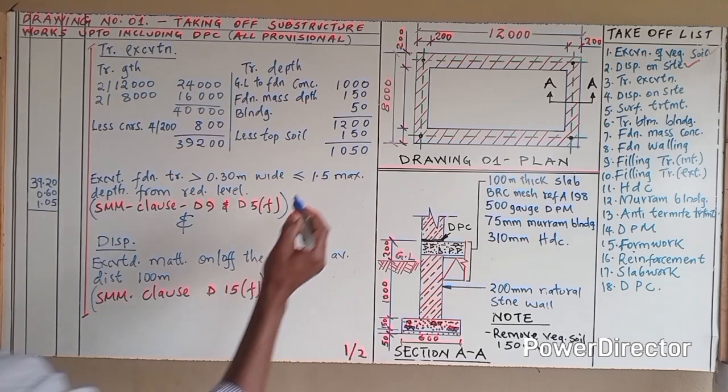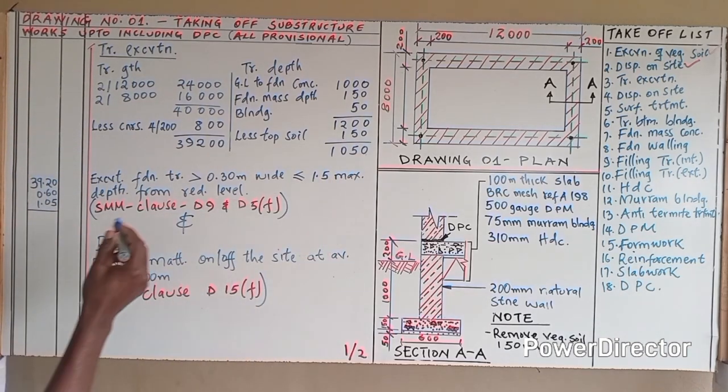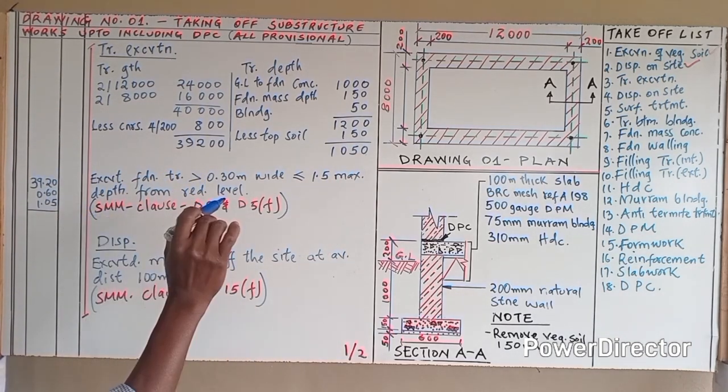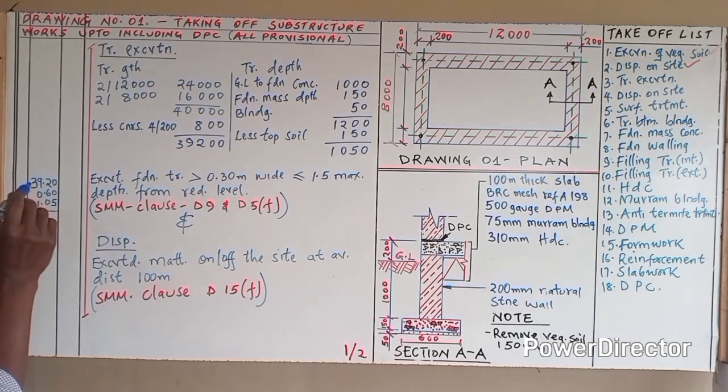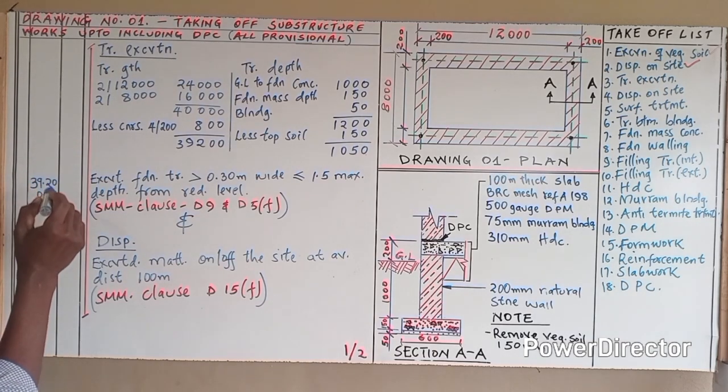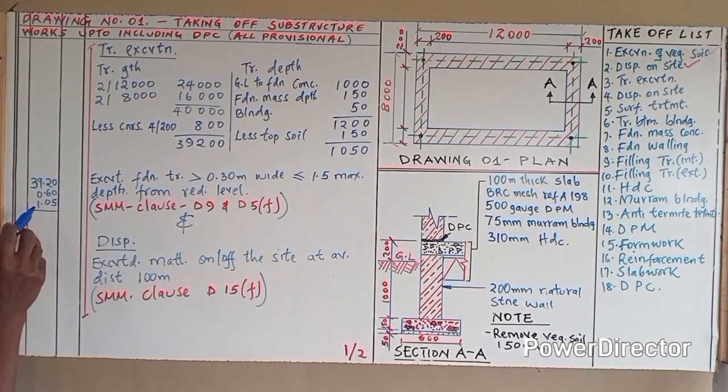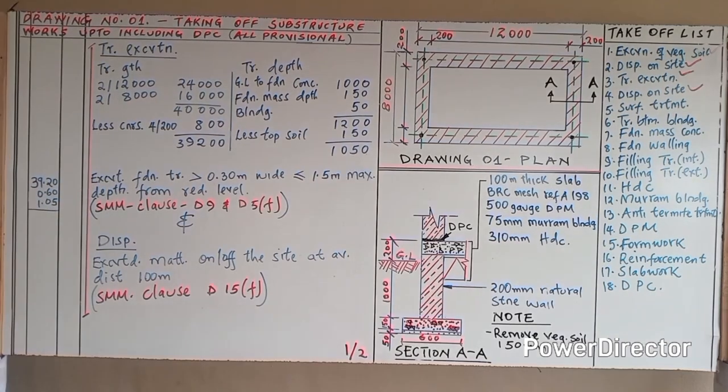So when we are booking here, with the measurements, start with the length and then the width. And the width here is 600 millimeters. Now, when we are booking this one, it is 0.60, followed by the depth, that is 1 meter, 0.05. So this is the depth of the trench that we are going to dig. So we have booked this one.